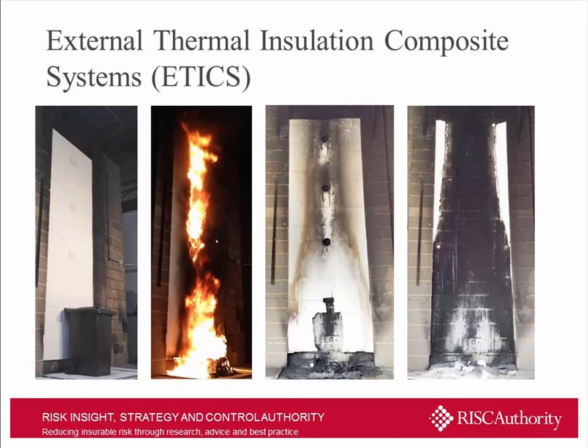But the two images on the right-hand side show an example where the render was punctured as if to install bathroom vents and suchlike. And as you can see, the damage to the insulation behind the render, and obviously whatever was behind it in the construction itself, would be badly affected, and more so than if the render remains complete. We were testing against a blockwork wall, so the fire went nowhere. But if that was a timber frame building, it could be a very, very different outcome.